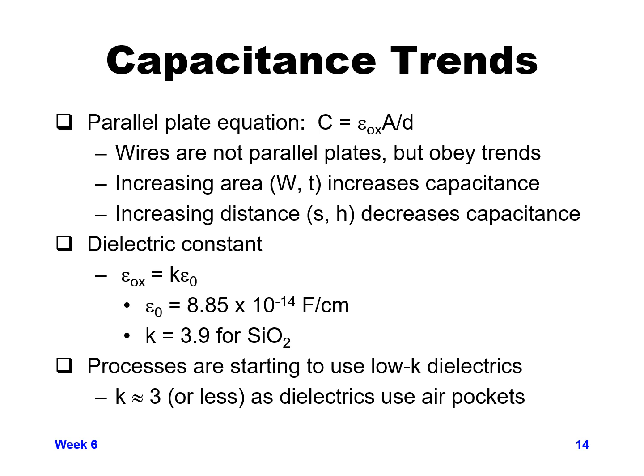So higher level metals tend to have lower capacitance to the layer of metal above them and the layer of metal below them because they have a thicker oxide between metal layers. And of course, your dielectric constant for silicon dioxide, the value of K goes into your epsilon oxide, which is K times epsilon 0, which is a constant, and your K for silicon dioxide is 3.9.